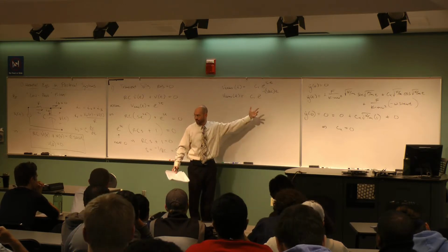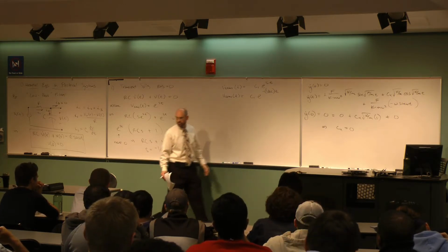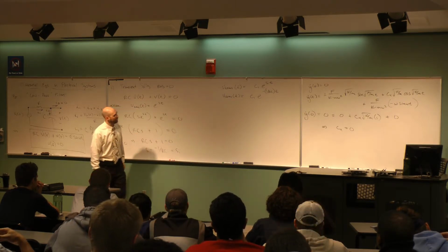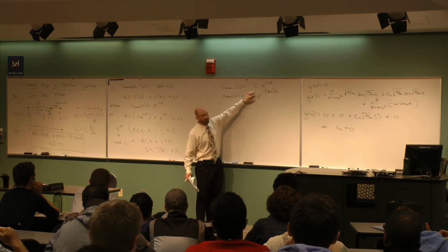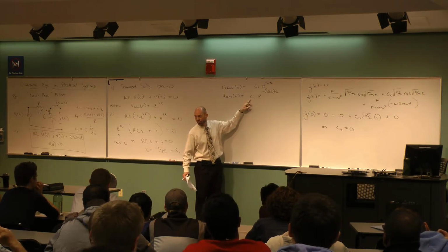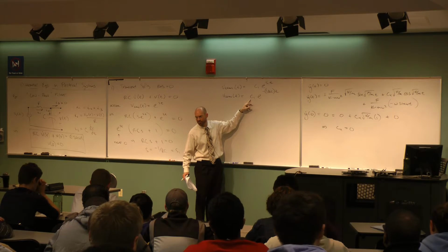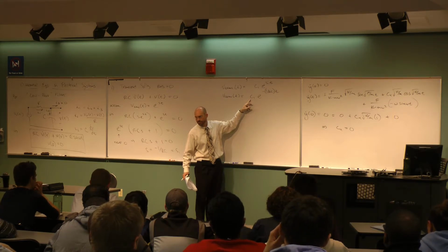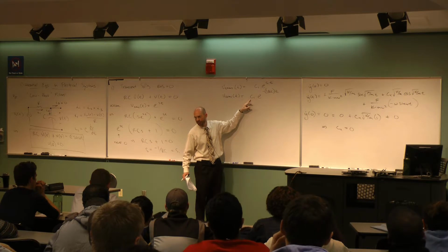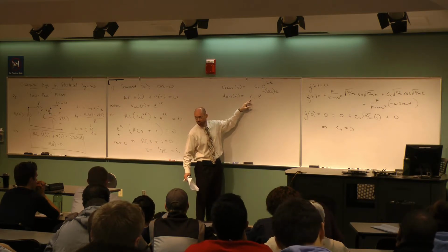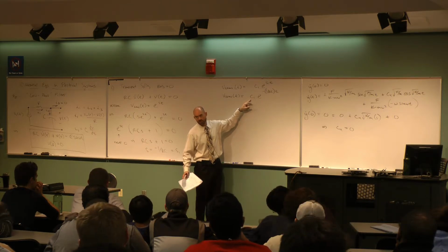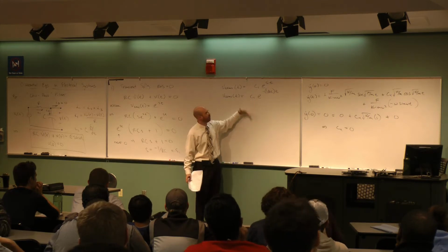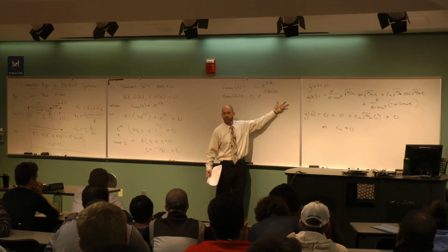Okay? How fast does this thing go to 0? What does that depend on? Does it depend on this guy? Does this say how fast it goes to 0? The C1 is what? So if this was a sinusoid, you'd call it the amplitude, but can you be more specific on an exponential? Let me ask you a leading question. What's the value at t equals 0? C1. Okay, C1 is the starting point. So it doesn't say how fast it decays, it says where it starts. So I start here, and then as t gets big, I go to 0.